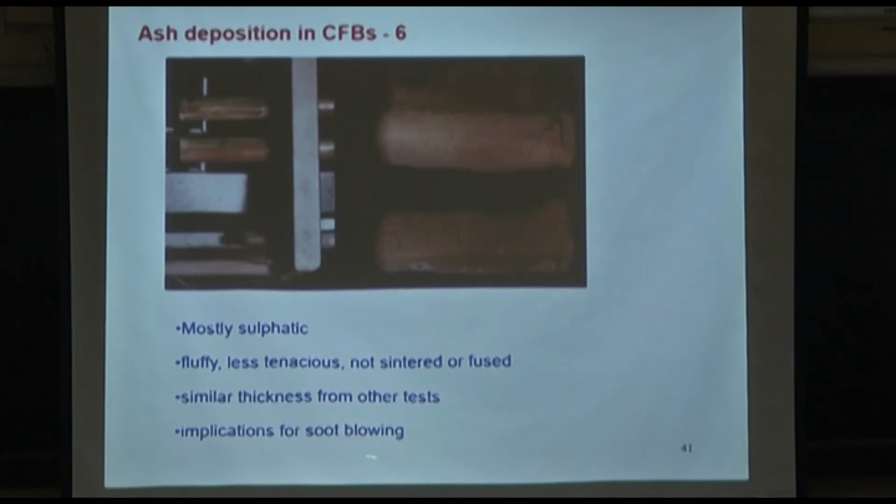So this actually gave us a strategy for the soot blowing. We knew after how many hours it builds up to such a level that it warrants cleaning. That's the information you need for soot blowing purposes: after that many hours you will have to employ the soot blowing. Obviously, you will not do the soot blowing every minute. Soot blowing reduces the temperature, so you will do the soot blowing only for 2, 3, 4 minutes at best in one go.